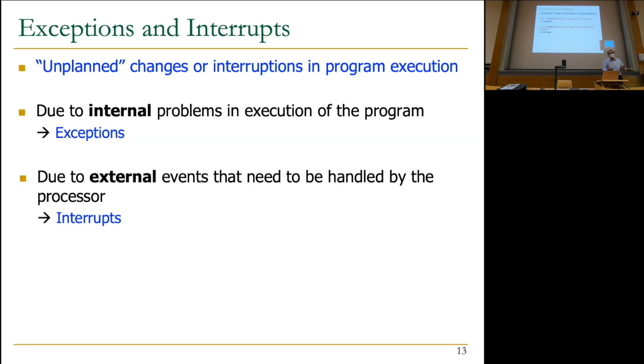With data flow, for example, the notion of interrupts doesn't mesh well with data flow architectures because in data flow, remember, everything's a data flow graph. An interrupt comes in, it's actually part of the data flow graph that's executing in the system. So everything in the system is a data flow graph. There's no notion of interrupting in a sense, right? It's just another input to the data flow graph. Okay, I wanted to make this clear because these are two fundamentally different things.